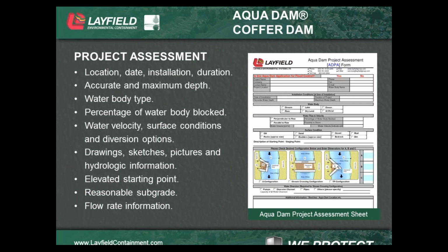We'd like to get an accurate and maximum water depth of the stream or lake that we're working in, just so we have a good idea as to, you know, during peak runoff season, what potential could we see there. And the installation duration plays into that, because if it's an 8-month installation, then we have to look at the 8-month window and determine, you know, where are we actually falling into as far as potential flows and water depths. Where are we actually going to be working? That's what we need to design the actual Aqua Dam to withstand.